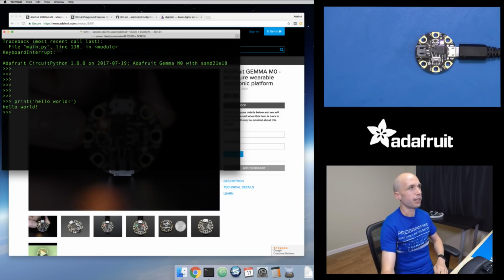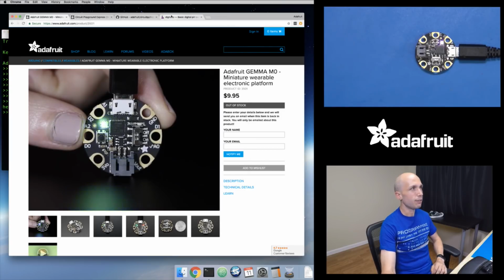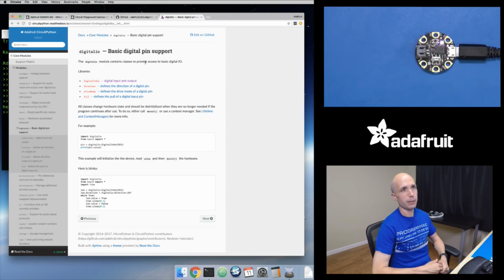With CircuitPython, the way that you talk to digital inputs and outputs is using this module called digitalio. I'll put a link in the description so you can go to this page. This is the CircuitPython API documentation. This is the module that we need to use. We're going to use this module, and it basically has one class inside of it that we care about.